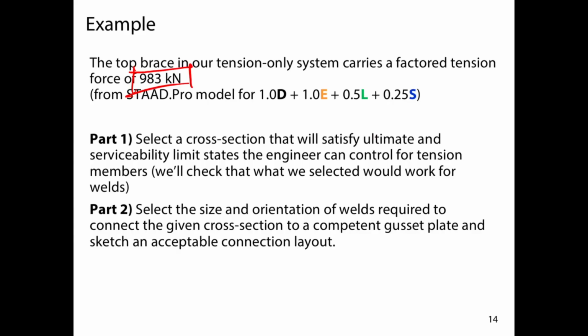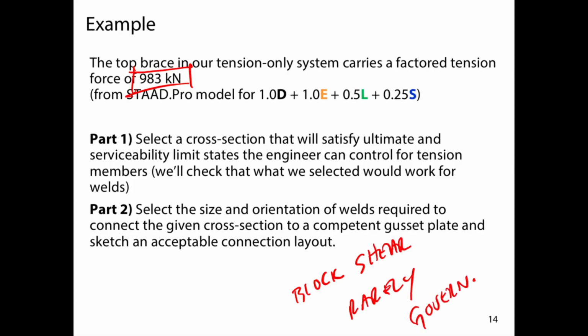Block shear is not going to be super important for us in this case today, but I think I show you the calculations in the example notes. This is one of those situations where, for the example we're going to be looking at, block shear is going to rarely govern. Okay, so it's not super important, but I do want to show you in the example notes how a block shear calculation might work for a fillet welded tension member instead of just a bolted one. So we're going to pick a channel that will work for welds and bolts. We're going to then design the connection using fillet welds.